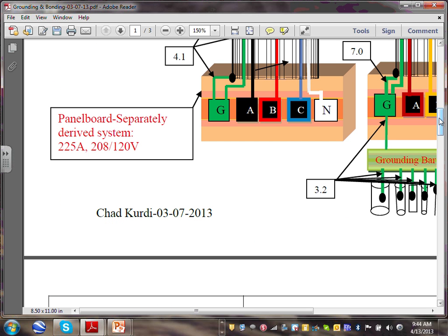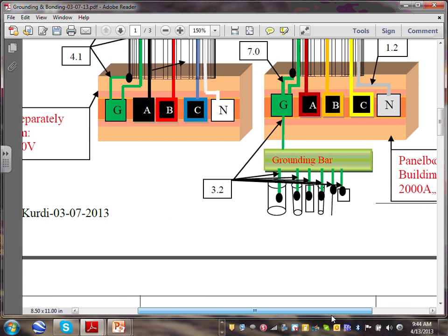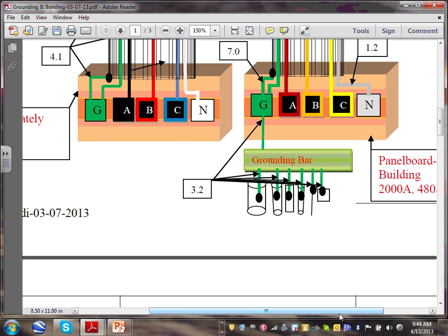Do we have power limited technician guys too, right? For the power limited technician guys, the code says you're required to provide an inter-system bonding device or equipment. It looks exactly like this bar, right by the service or this connector or the meter, for the low voltage guys to go and tie their own. It used to say grounding conductor. Now it's grounding electrode conductor or bonding conductor. So you have to have an inter-system bonding terminal so you can tie the low voltage stuff into the system.